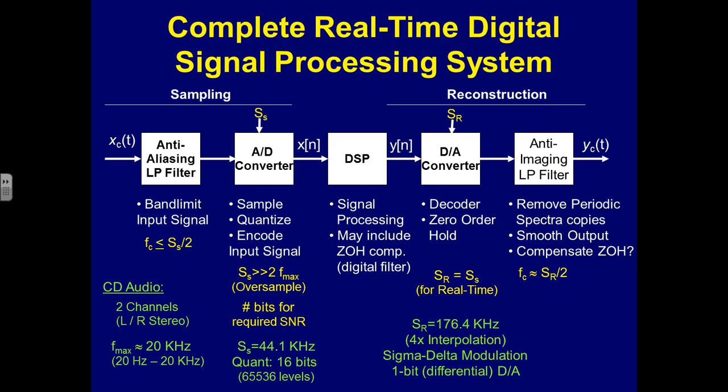So again, the whole process of digitizing is more than just an A-to-D converter and D-to-A converter. Up front, we have to have some kind of anti-aliasing filter to make sure that the signal coming in doesn't have frequency content that's going to alias or hasn't picked up noise somewhere that's going to alias. So that's a low-pass filter that band limits our input signal to the Nyquist rate or less, then followed by an A to D converter, which sometimes requires sample and holds.